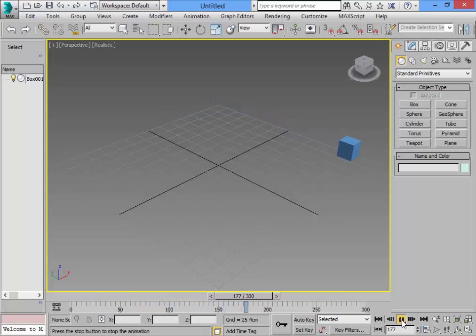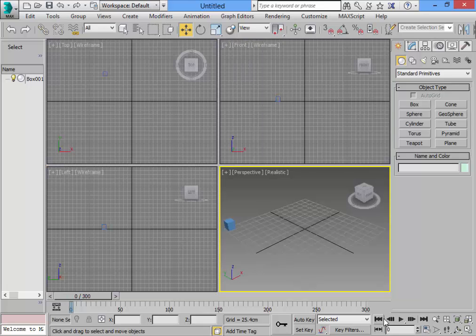That's good. And do you remember that I had clicked one button for the active viewport only. Now I'm going to see all the viewports. I'm looking in all the viewports, but just this viewport is enabled now because it has a yellow border. When I play, it is just changing this box without changing the others. So that makes less calculation, which means using the resources of your hardware efficiently.